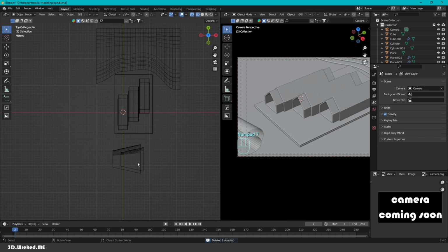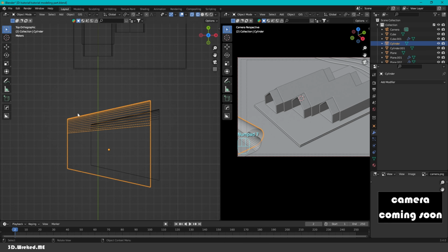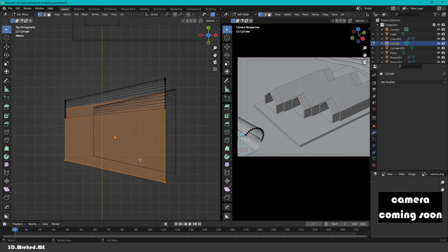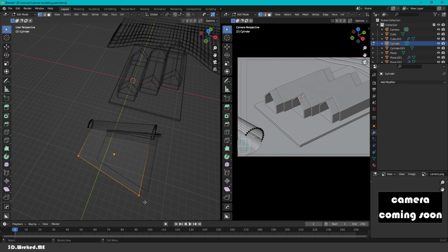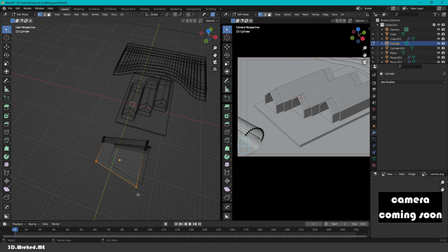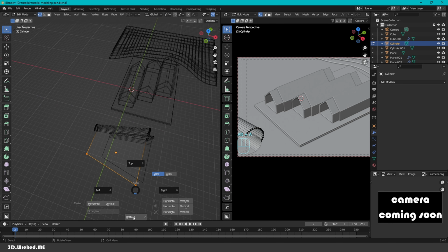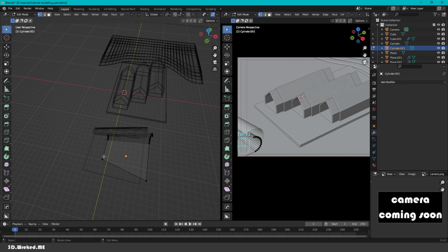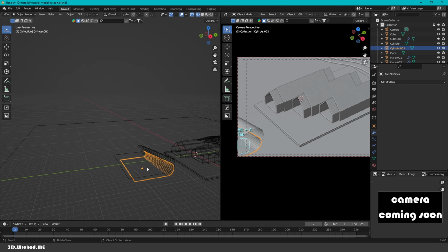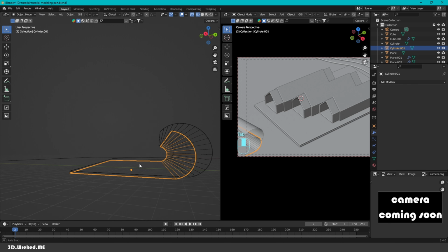So if we go into top view, maybe we overdid it, but let's select this one and this one, and then Alt A and go to bottom. This is the align from Mesh Machine, Alt A, bottom, and this will be okay.